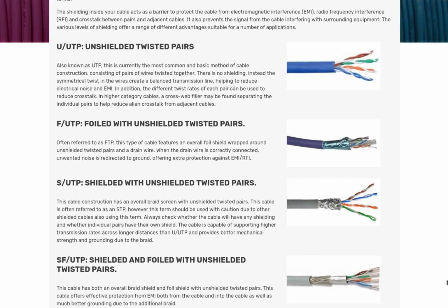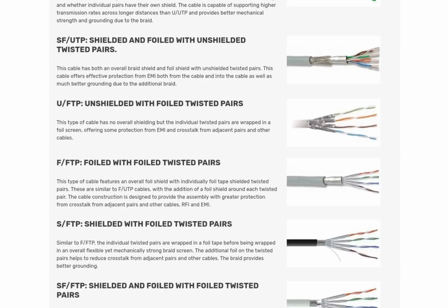The next step up in performance is to add some shielding to those 4 twisted pairs. So you can either add a layer of foil around all the cables to shield them from external interference, or some copper braid, or both. And that will obviously screen out, give you your Faraday's cage effect to shield out any noise. Next, what we can do is to stop crosstalk between the various communication channels by shielding each twisted pair. And you can see that here. So here, each twisted pair is wrapped in its own foil shield. And then, as we did previously, we can add a copper shield for the whole cable, or braid, or both. So basically, we're adding increased levels of shielding to the cable and the individual channels within that cable. And that will help improve your signal to noise ratio, which will hopefully reduce the number of packets, the number of bits that are corrupted by these noise sources.